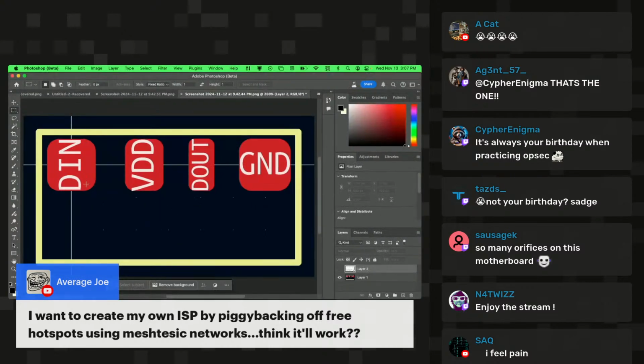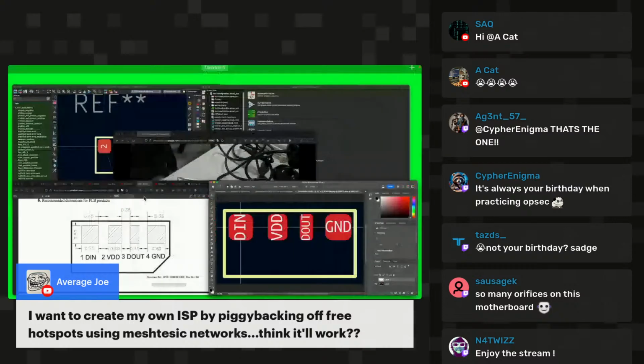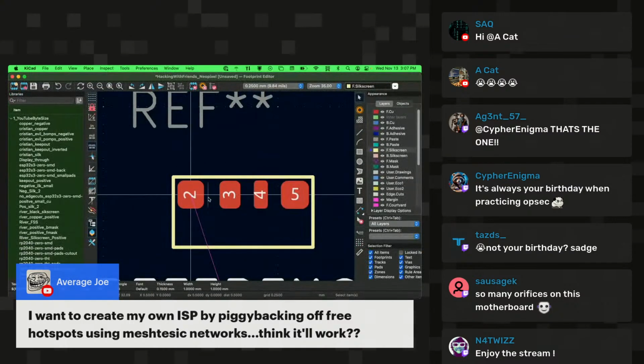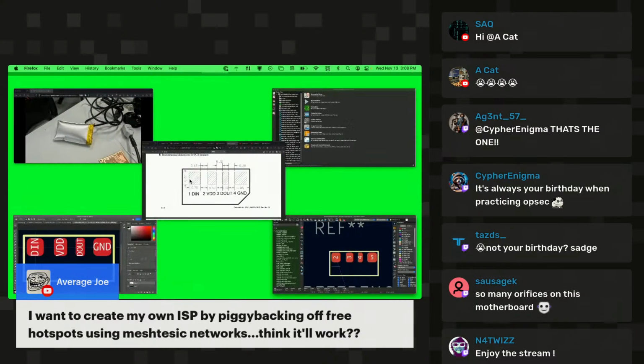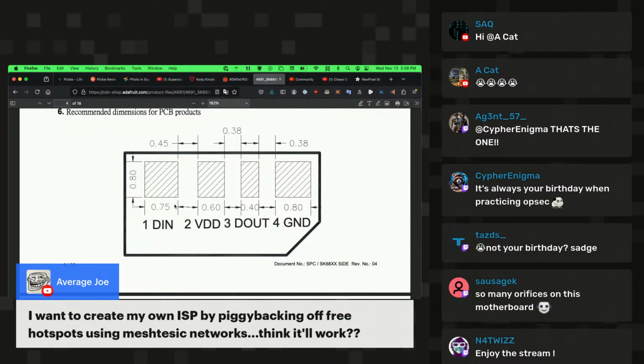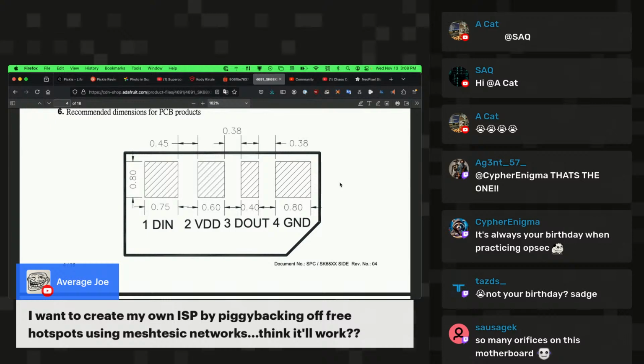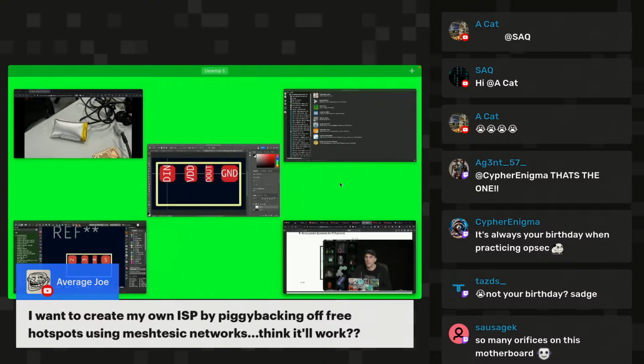I did this shortly before, and I want to show you the result of that. This is the result where everything is spaced properly, I think. The way that I did this was setting the origin to basically the center of the pad, and then referring to this data sheet in order to make the necessary calculations to place each one on an x-axis. That is so boring to me to say out loud, but this saved me like an hour of my ADD brain running around in circles and screaming because it didn't understand why nothing was measuring up.